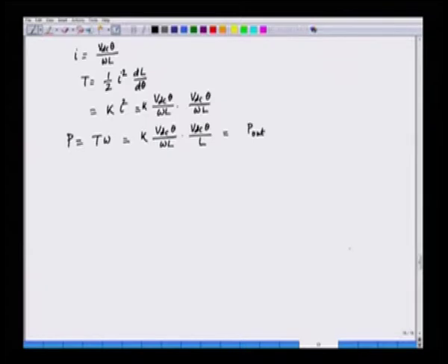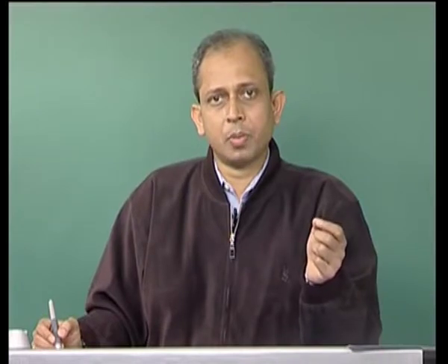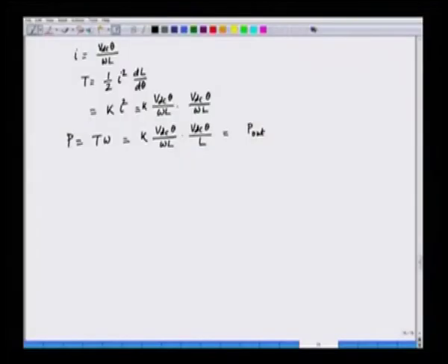Now when we operate a switched reluctance motor, it is operated in various modes. When the speed is very low, current will rise quickly, because we have already seen the expression for the current. And we see that if omega is small, close to 0, I will rise very quickly, and if omega is medium, the rate of rise of current will not be that fast. If omega is large, the rate of rise will be still low. So I depends upon the speed.